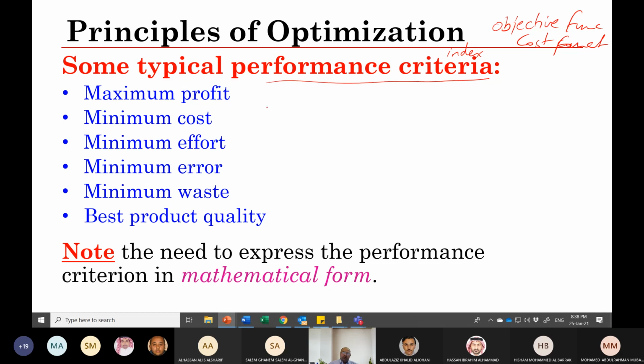So this is called the objective function, as I mentioned. If you have, for example, time, or for example, error, especially in the control area, usually when you design a PI controller, and you need to optimize how much KP and how much KI in order to minimize, for example, the integration over the time of the error squared. The error squared could be, for example, delta omega.